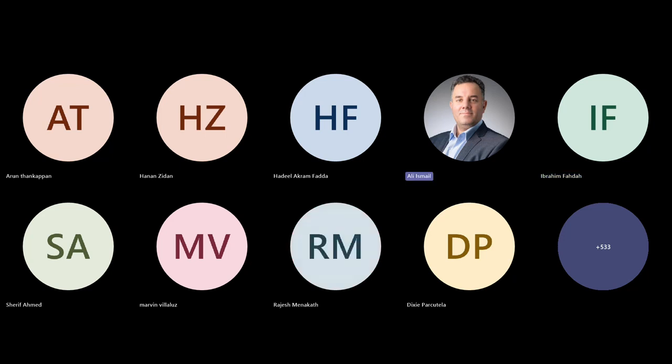Okay. Relating to the question of how to check the fire rating if the finished materials are not considered: the same case applies to what you are doing now when you submit to Civil Defense, where you indicate the fire resistance of internal walls, external walls, stair walls, emergency doors, etc. So it is just a parameter where you indicate if the fire rating for this wall is 1 hour or 1.5 hours, etc. So it's just like a parameter.